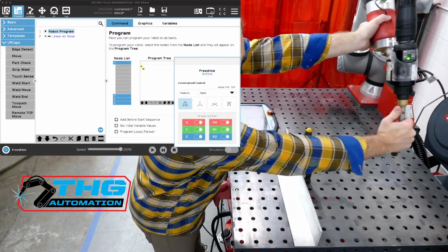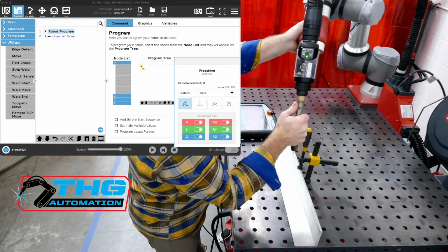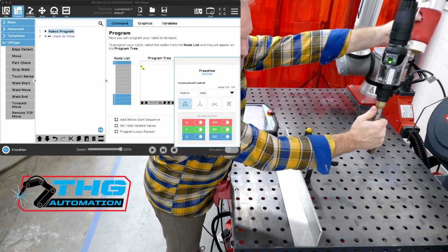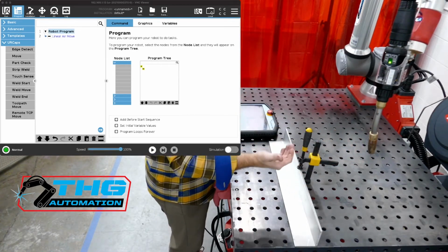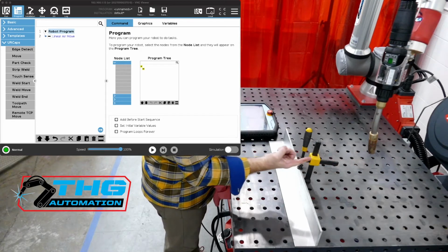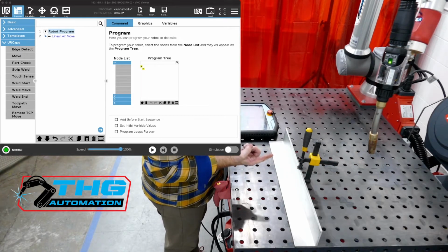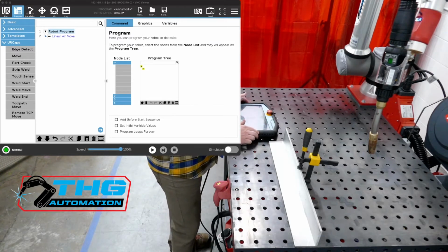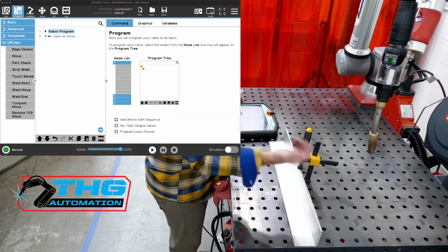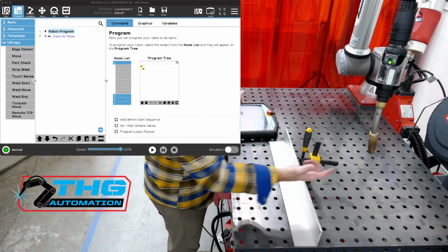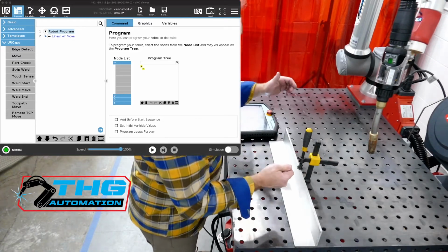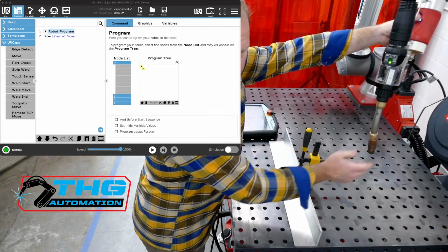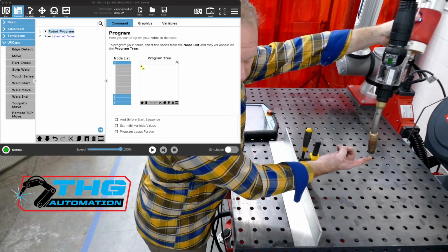For an example, if you see across your screen, I'm going to move the robot in a linear motion back and forth, right? The controller is calculating or solving the motion while making a linear path in a direction from where it's at to where it's going to go. In this case, let's say we want to make this move as fast as it can from one place to another, not taking into account where the torch is. To do that, we're also going to create maybe some wild moves on the end of the torch, because the robot controller doesn't necessarily care about making a linear path.